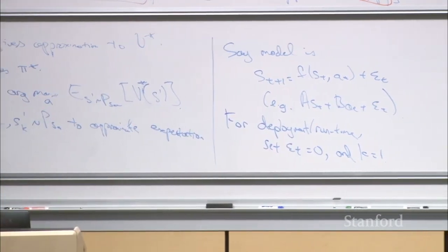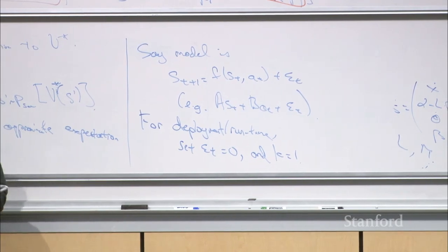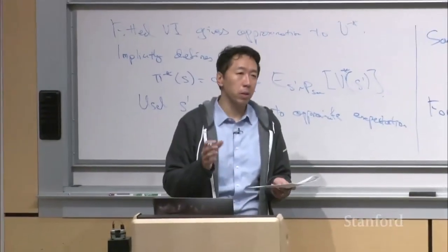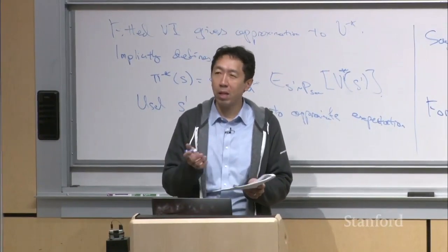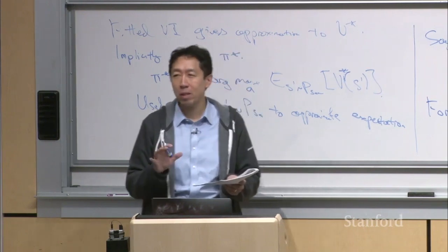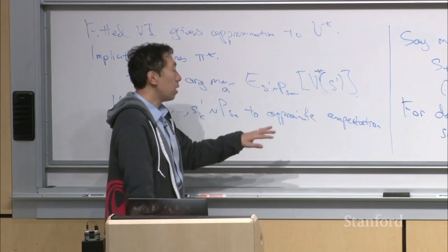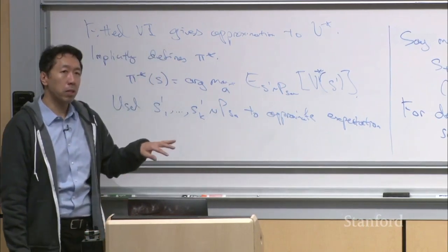And so this is a reasonable way to make this policy run on a helicopter, which is, during training, you do want to add noise to the simulator because it causes a policy you learn to be much more robust to little errors in the simulator. Your simulator is always going to be a little bit off. Maybe it didn't quite simulate wind gusts, or when you turn the helicopter, does it bank exactly the right amount? The simulator is always, in practice, a little bit off. So it's important to have noise in the simulator in model-based RL.